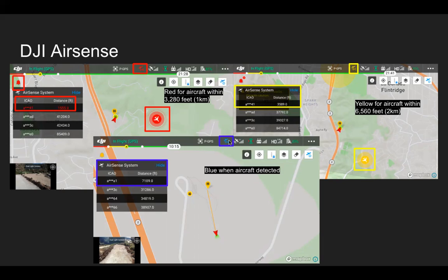And then also now talk about the indicator at the top of the app here. We can see it changes color as well, along with the aircraft that's shown on the map. Red, yellow, and blue. And just a quick review, we can see we now have 17 satellites connected. We can see vision system, RC signal strength, video transmission signal strength, and battery life on the top there.